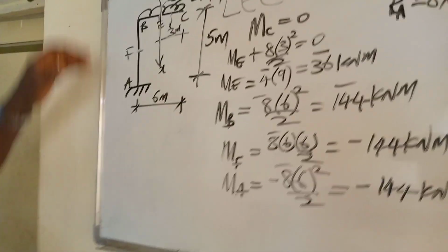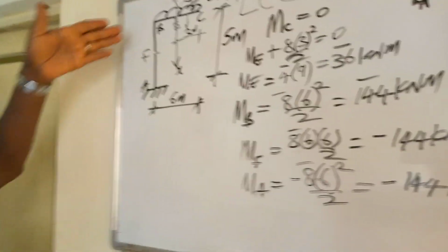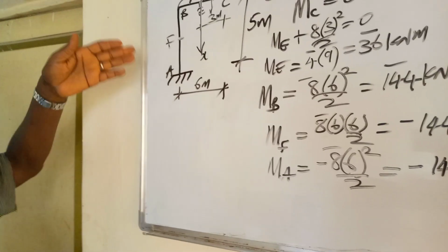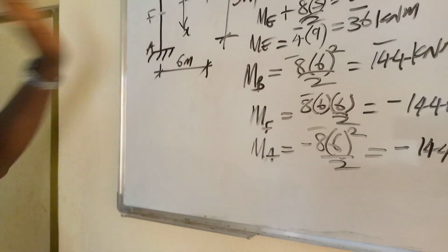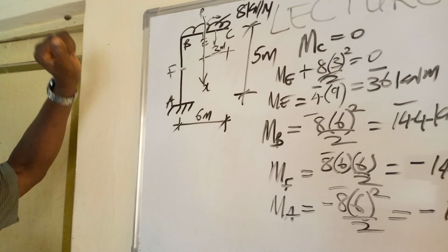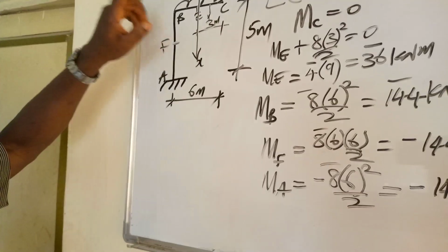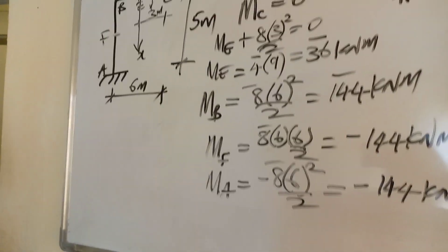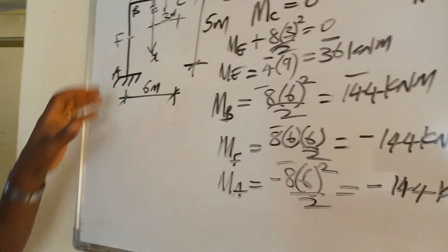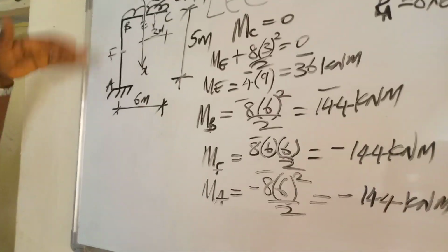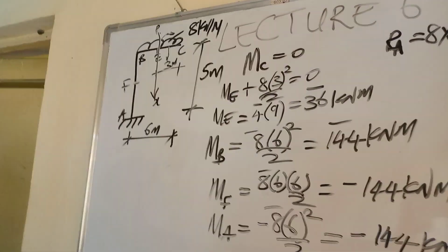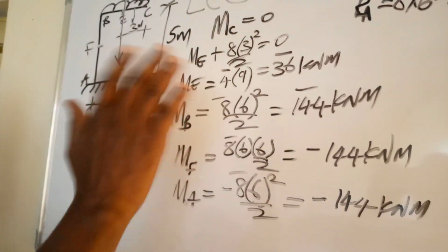Even when we're taking moment along BA or BF, we can't multiply with BA or BF, because BA or BF is not perpendicular. The one that is perpendicular is BE, EC or BC. That's why the moment continues giving the same value as I move along BA. Such a moment, from point B down to A, is called a concentrated moment. It's giving you the same value.